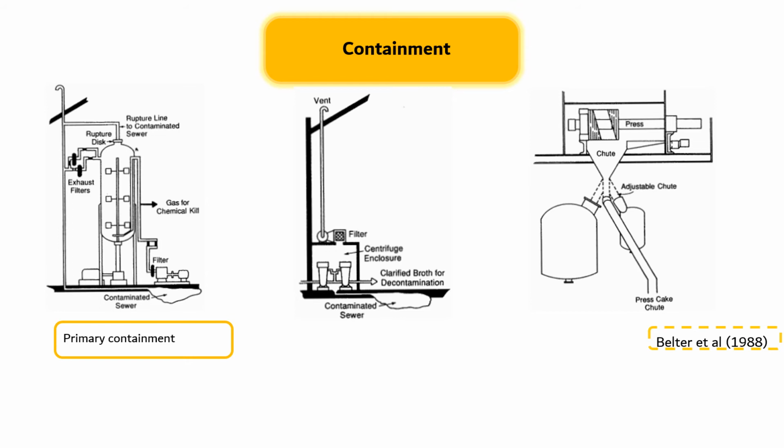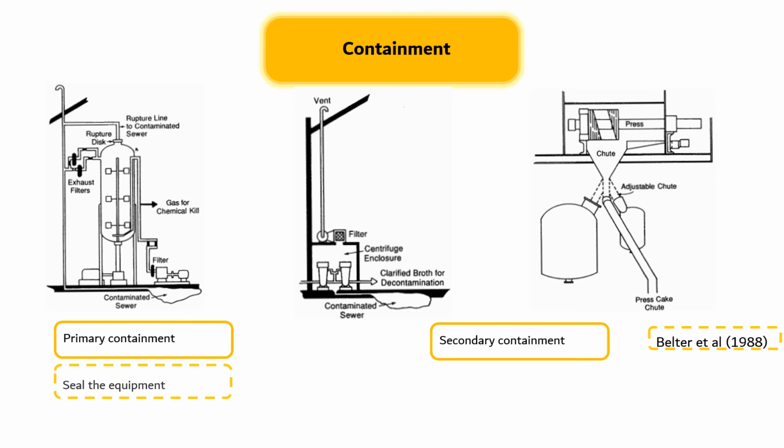The fermentation vessel is contained in the sense that cells are sealed inside the vessel and not allowed to be in contact with the environment or personnel until they are killed either thermally or chemically. These facilities are designed to contain accidental leakage of live cells in special locations so that the escaped organisms can be killed before they contact the uncontained environment.